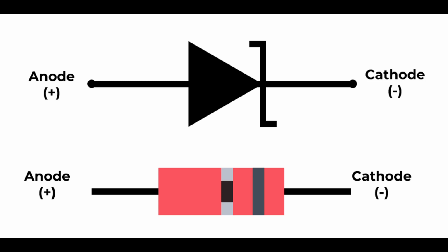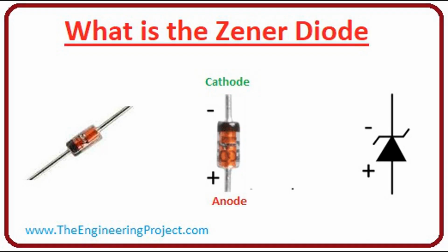Digital logic level shifting. In digital circuits, level shifting is often necessary when interfacing components that operate at different logic voltage levels, for example 3.3V and 5V. Level shifting can be accomplished using dedicated level shifting ICs or with simple transistor-based circuits. Zener diode clamping. As mentioned earlier, Zener diodes can be used to clamp a signal to a specific voltage level, effectively shifting the signal's reference voltage.